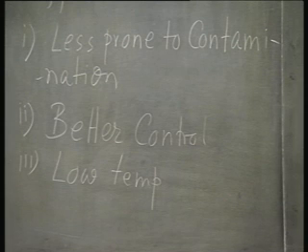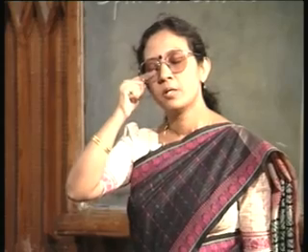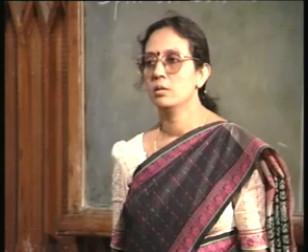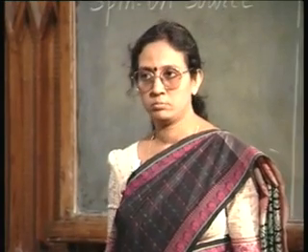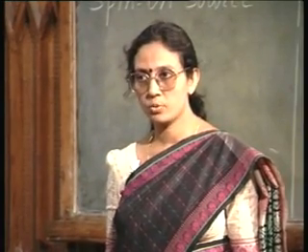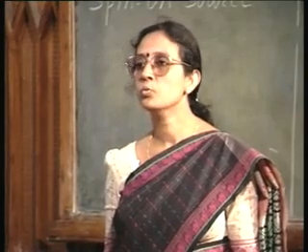Then again, there is the question of flexibility. In case of diffusion, you know that, well, at most I can get the solid solubility limit on the surface for the infinite source diffusion, and then as I do the drive-in, the surface concentration is going to go down and the junction is going to move in.